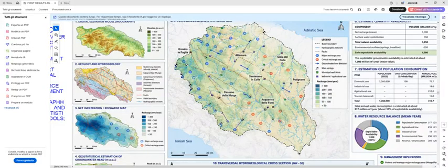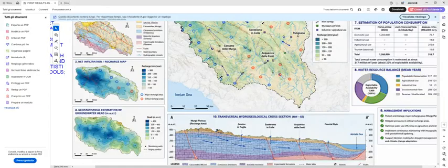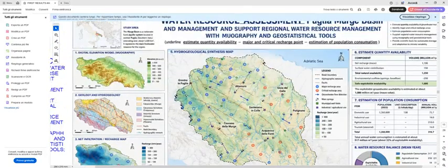by year. So the measure infiltration occurs in this central part, also for topographic conditions, but also for the permeability of the first surface layer. We have a geostatistical estimation of the groundwater depth, the top of groundwater. So the deepest part is in this part. We have also plotted the monitoring wells and the kriging contour.